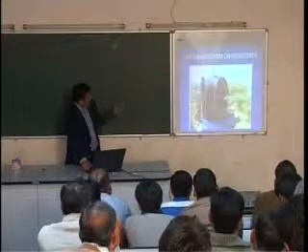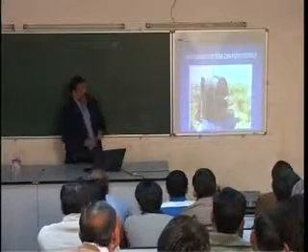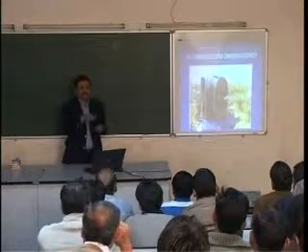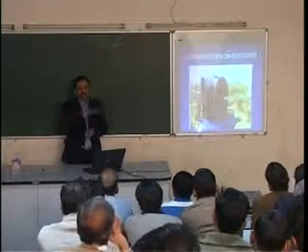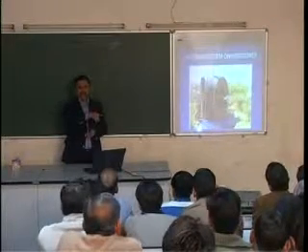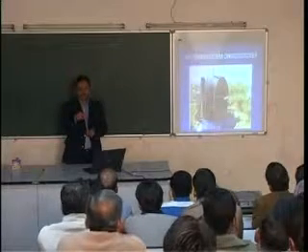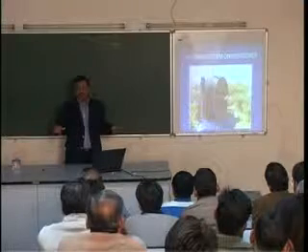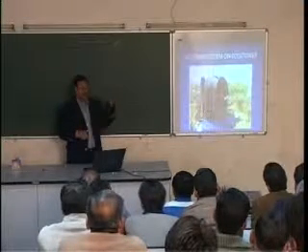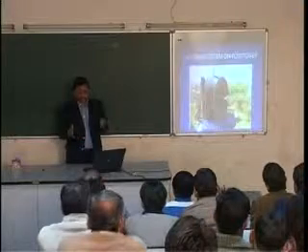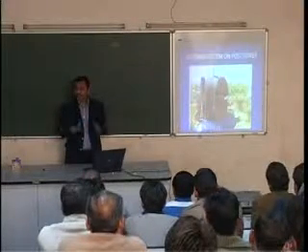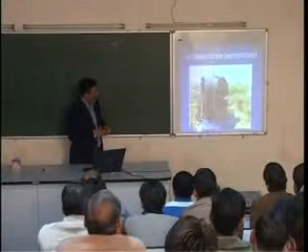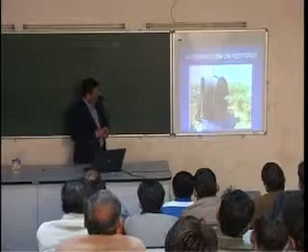But today, this is the one which is kept on a positioner. I saw yesterday in your lab you have one probe; Dr. Patnaik showed me that you are moving the antenna and then you can record your amplitude and phase, or probably the signal strength, and you can note down the angular information. But what we need, as I showed you first, is that the antenna radiation pattern is not a single cut; it's a three-dimensional cut. You have to go in theta and phi in all the cuts. You have to take. So that is why you put the whole thing in the positioner.